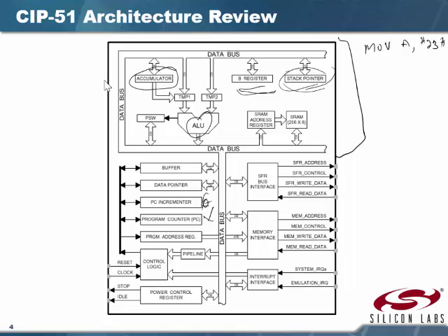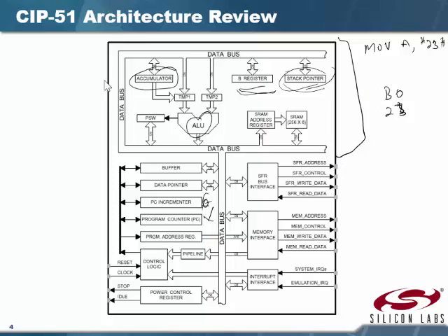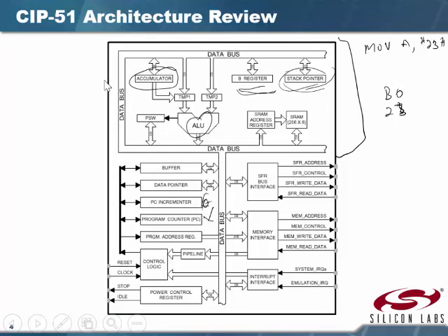If I want to take the time, we can look up the opcode. But what that's going to store in memory is B0 23 right there. So the program counter is counting, and right there, the program counter is counting here, and it needs to skip this instruction. So it has to add not 1 to the program counter before it does the next instruction. It has to add 2, because the next instruction is going to be here, right there. So that's the job of the program counter incrementer, right there.